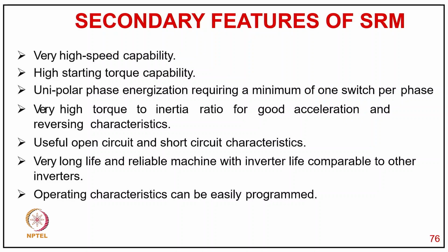Unipolar phase excitation requires a minimum of 1 switch per phase. Very high torque to inertia ratio for good acceleration and reversing characteristics. Useful open circuit and short circuit characteristics. Very long life and reliable machine with inverter life comparable to other inverters, and operating characteristics can easily be programmed.